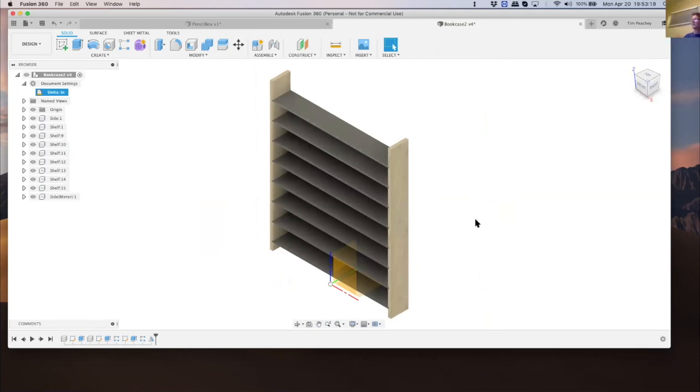So what I've done is I've done the top-down design approach. I had a rough idea what my bookcase was going to look like, enough to figure out what most of my relevant parameters were. Now, when I go to put in the kick plate, for example, I might realize I want the kick plate to be recessed, and I don't have a parameter driving that. I don't have to have a parameter. I can put in a number, but if I want to maintain this purely parametric model, then I should do that. And actually, I'm going to do it because it demonstrates one little point that I haven't really demonstrated yet.